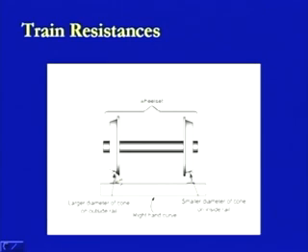Of course, it is going to help as far as the movement is concerned, because we require a larger movement on the outer side of the curve as compared to the inner side of the curve. So because of this larger diameter, the circumferential movement will also be more, whereas because of this lower diameter, the circumferential movement will be lower, and that's how this differential value will come into the picture. And we are going to use this differential value to find out the resistance in the case of the curves.